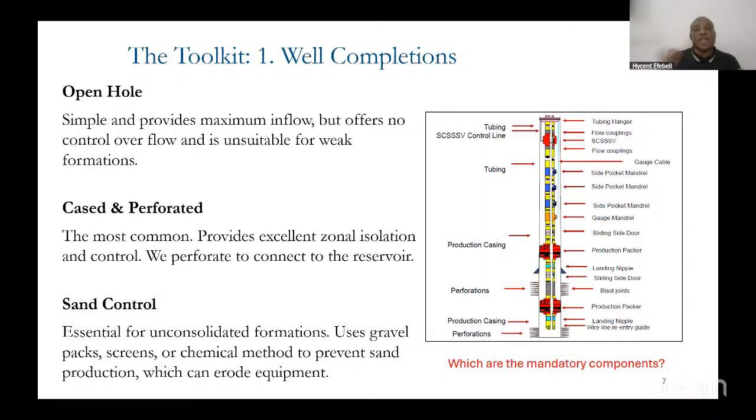We can have casing, slotted liner, or cemented liner, cemented and perforated. That is good in a consolidated formation, but it reduces the surface of the reservoir that we are exposing to flow. So you need to think about those when you are designing your well.